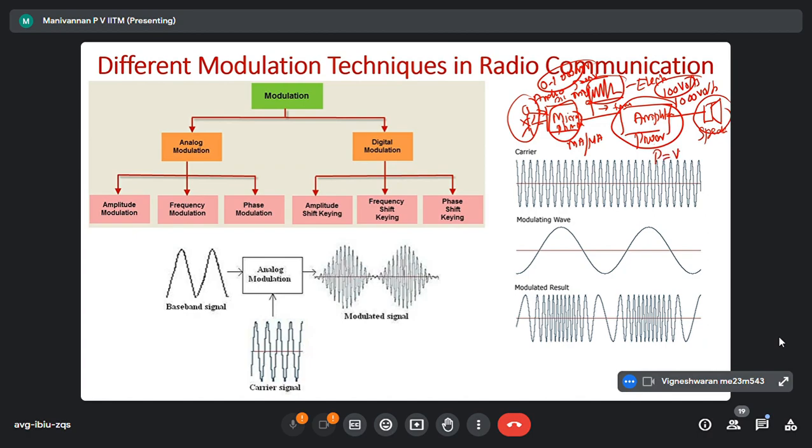Power equals voltage times current. Say, for example, 500 millivolts, 500 into 10 power minus 3 volts, correct? This is the microphone signal, I say Vm. What is Im? The microphone current, maybe 500 microamps or 5 milliamps. Even that is a big number, right? That's what it generates. What is the power generated? We take 5 milliamps. So P microphone equals V microphone times I microphone.